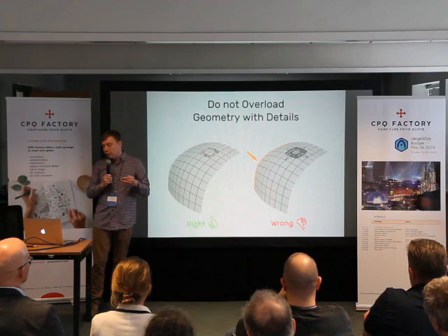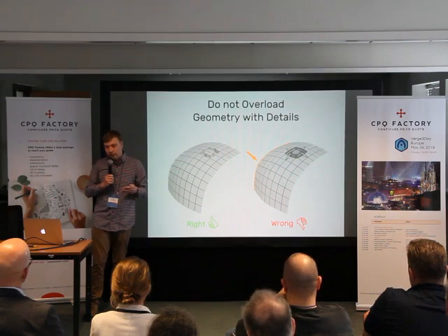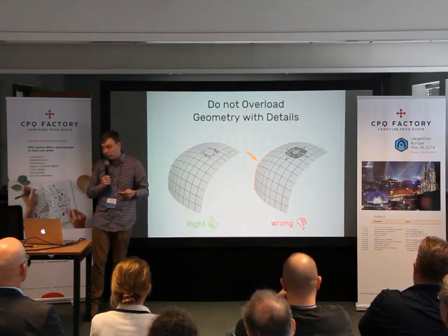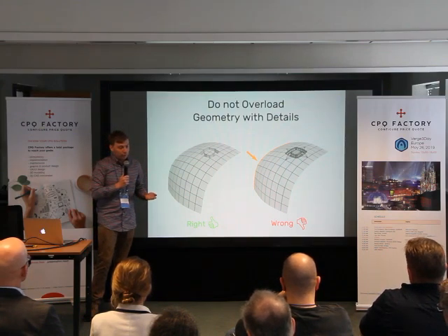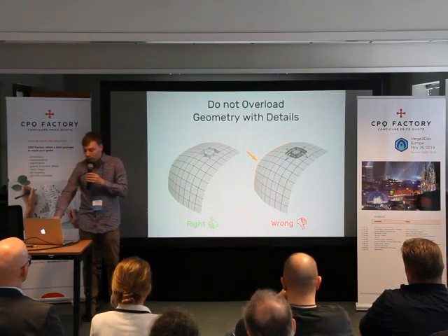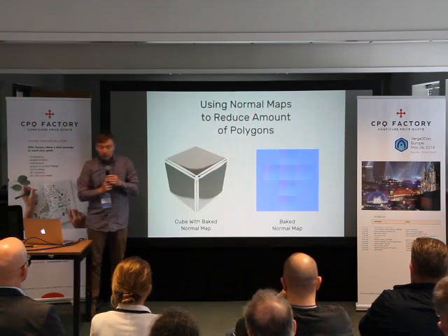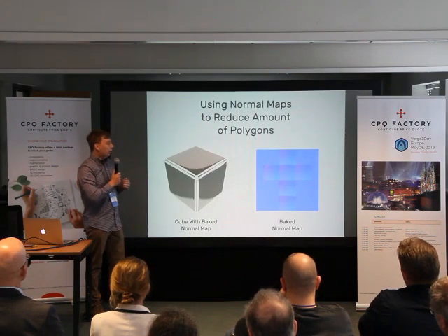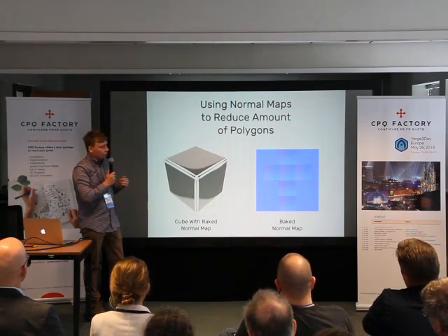Even if you zoom closer to it, you will see a better result on its sides for the reflection, for the specular. So the solution is to increase the amount of polygons for the border or decrease the amount of polygons for the detailed part.